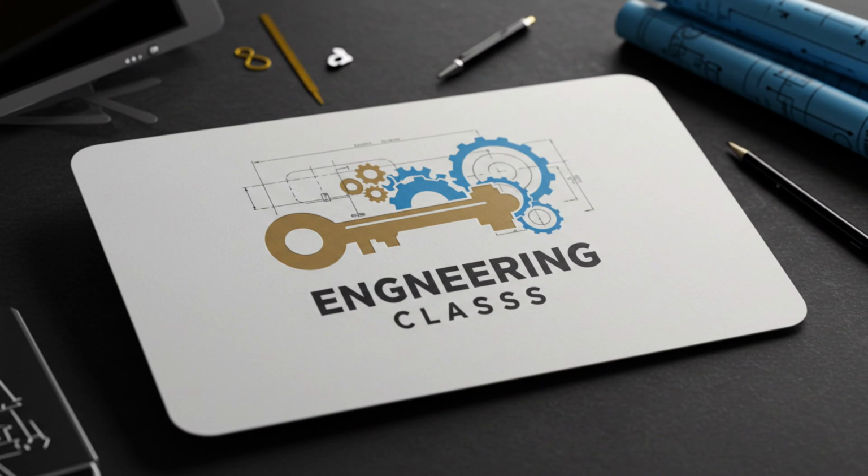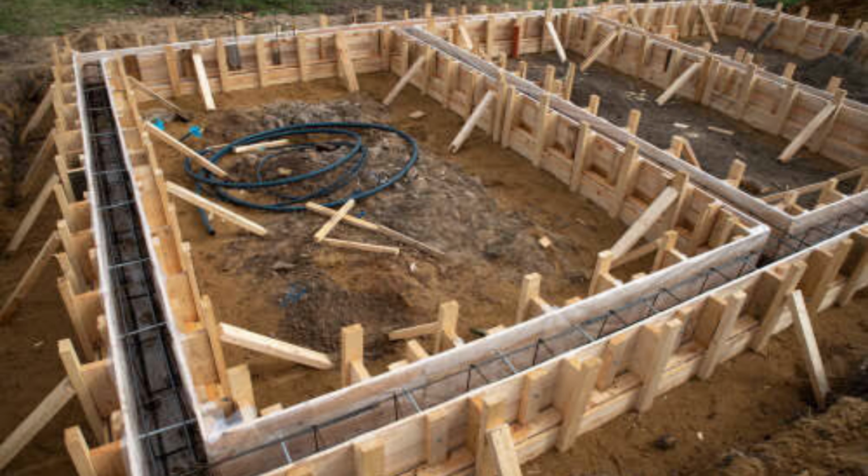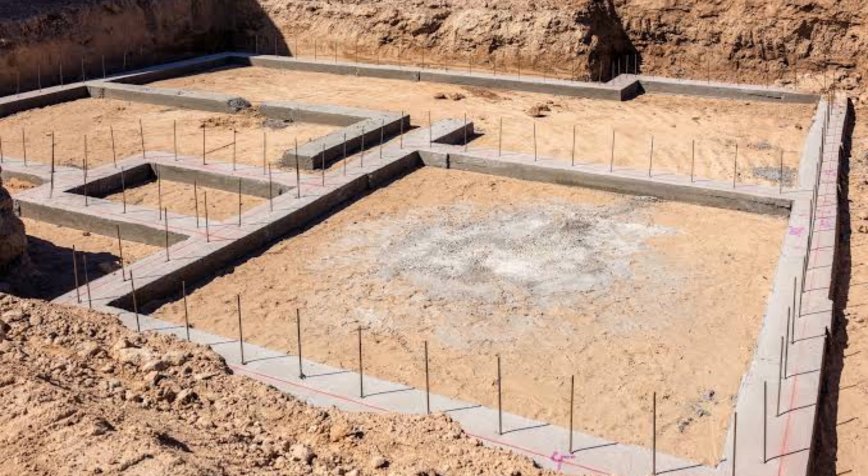Welcome again to our engineering class, and today let's discuss the base of the building: foundation and foundation plan. The concept of foundation. Foundation refers to the lowest part of a building, which is in direct contact with the ground. Functions of the foundation: 1. Provides the base for superstructure, 2. Transfers the load of the structure to the ground so that it stands firm and stable for its lifespan.